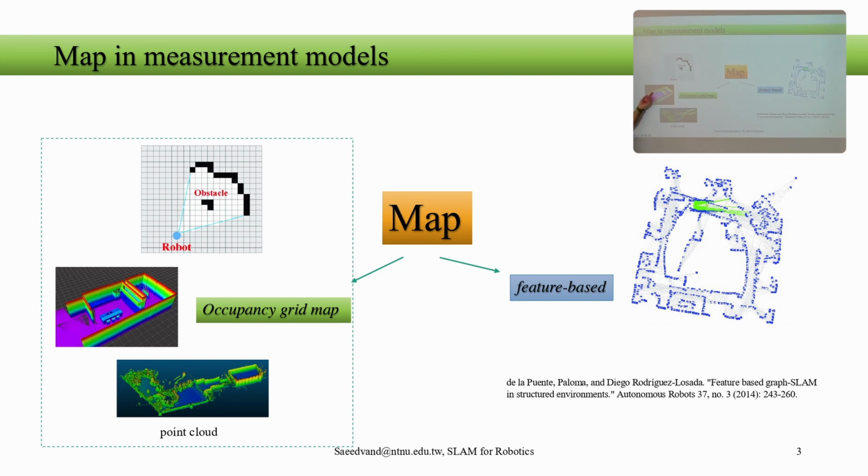Like if you're detecting a wall, you can extend it to three dimensions. But on the other hand, the realistic form is that there is a window. And of course, if you have a window, maybe the robot is a drone and can fly outside through the window. Then you need to have a real 3D model of the environment, based on the 3D construction that comes from, for example, a laser scanner.